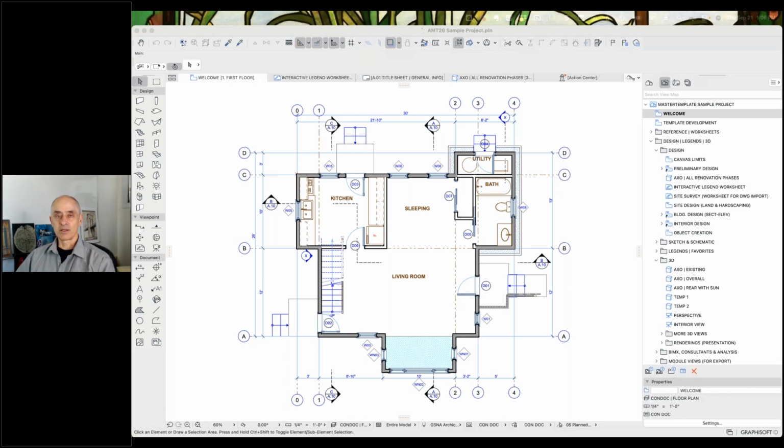The big new feature, from what I heard and what they posted on their website, is the tools to be able to do different design options very gracefully, with dedicated functionality for picking different areas. Maybe you have 3 different versions of the kitchen and 2 different versions of the back of the house, and you can mix and match and say, what if we had version A of the kitchen and version 2 of the back of the house? These are things that can be done in current versions of ArchiCAD, but require a lot of workarounds with layer management or renovation filters or some combination. And from what I gather, they've got a pretty good solution in terms of the tools.